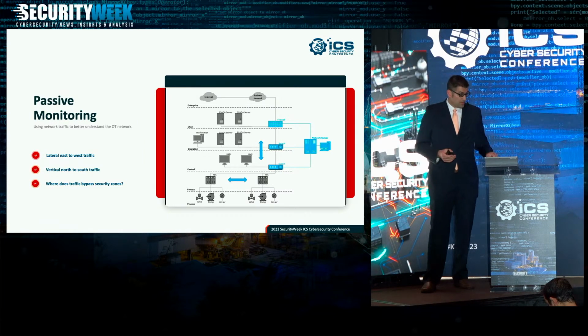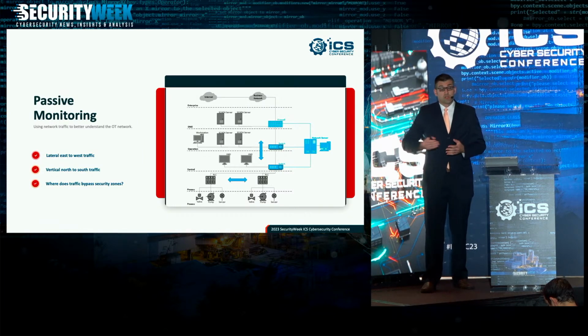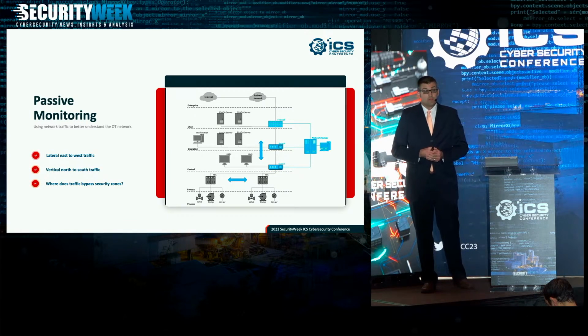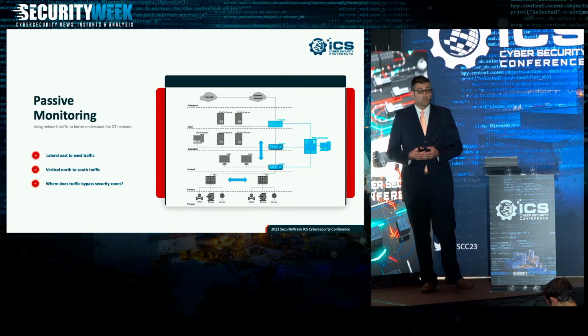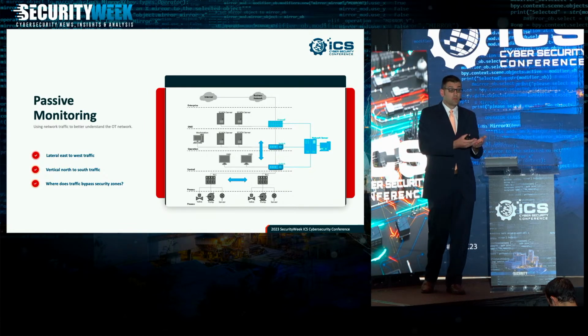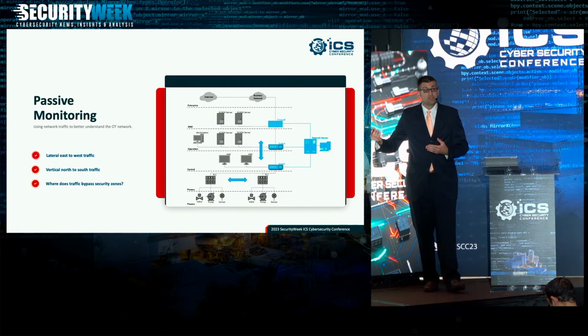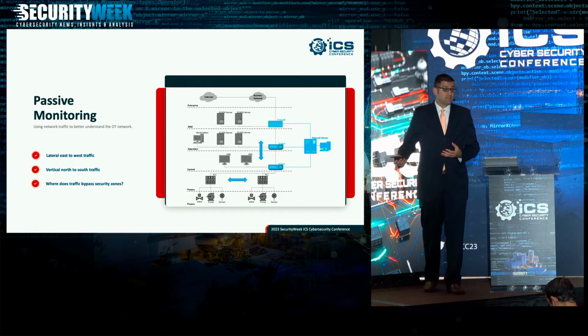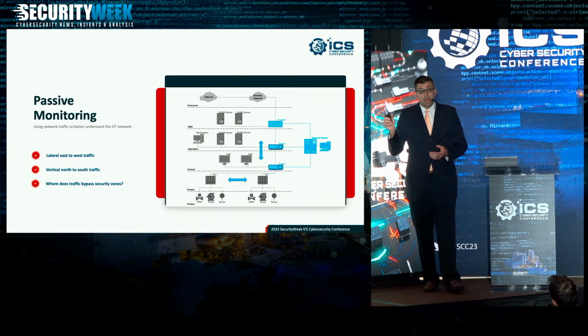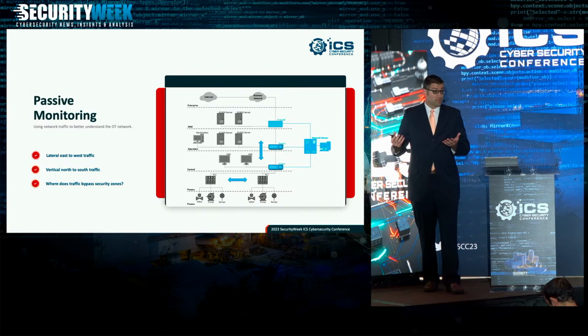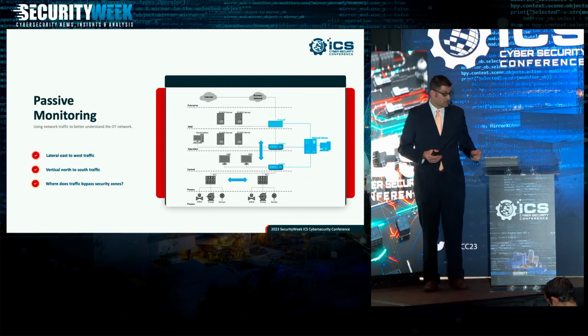Another thing we found out were certain meters, flow meters were installed, and they had Bluetooth capability enabled by default, with default passwords on those. So anybody that was walking up close by could pick those up. But because of the passive monitoring system, we now knew those devices existed and that particular model came with Bluetooth enabled by default, able to go and address and fix those.